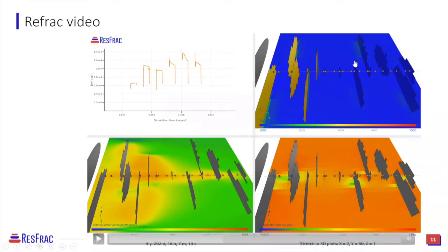So when we expanded the model from one stage, which was originally on the right-hand side, to 2 stages where we added this left-hand portion of the lateral, I did not shut off my existing fractures, or perforations rather, when I started to inject. So what we're actually seeing as this pressure on that first stage is the reactivation pressure for existing fractures. I know that had been a question last week and something to look at.